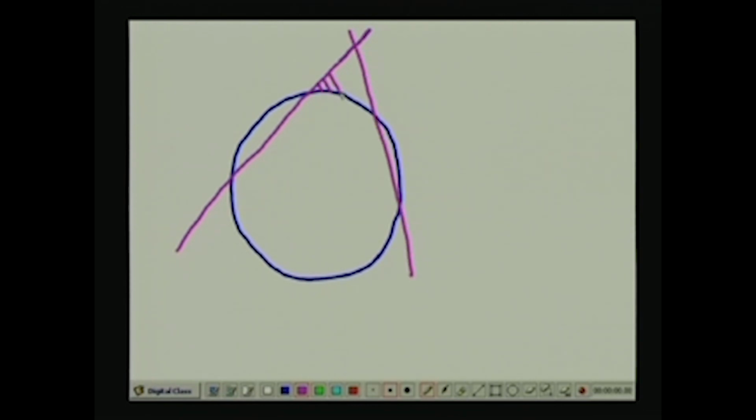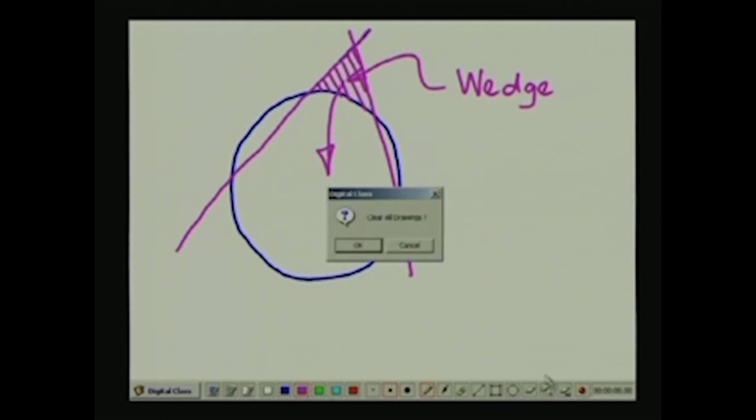Then as soon as the tunnel opening is made, this particular wedge of rock is going to fall over into the opening that is made. Now, there is another possibility, that this is not always going to be the case, because we could have a joint set that is oriented in a different manner.